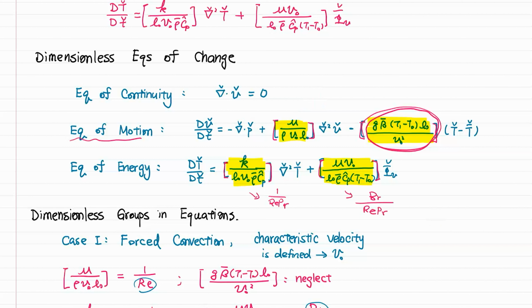So if you don't have a huge velocity gradient, you can simply compare the Brinkman number, whether it's much greater or much smaller than 1. If it's much smaller than 1, you can neglect the viscous dissipation term, and then you can consider all your energy transport going through convection and thermal conduction.